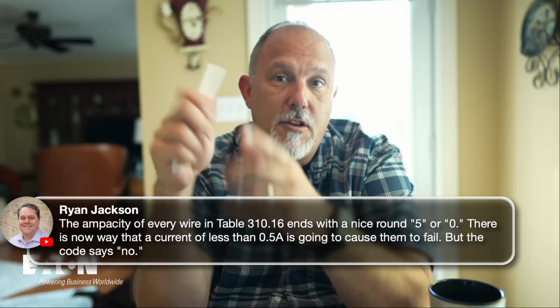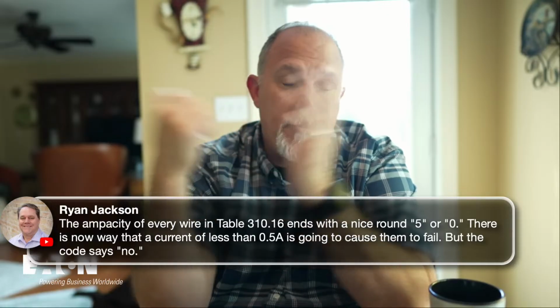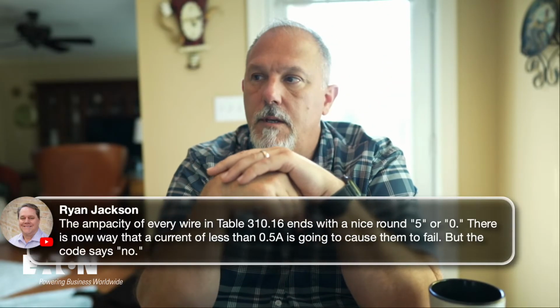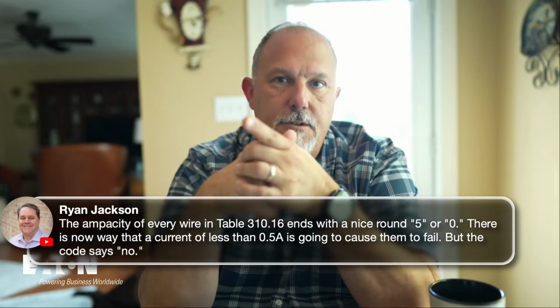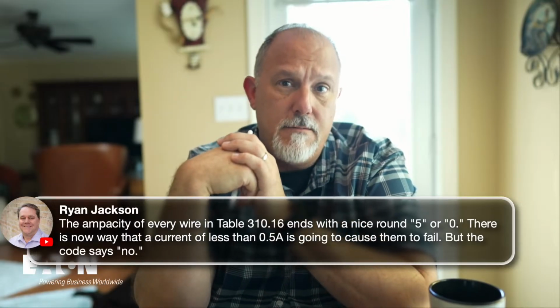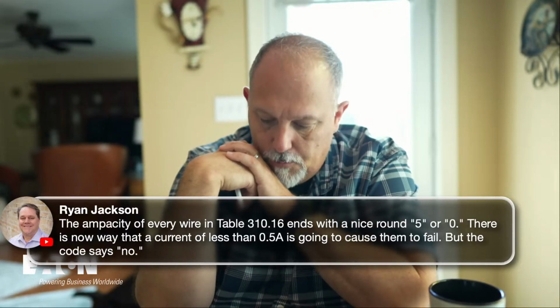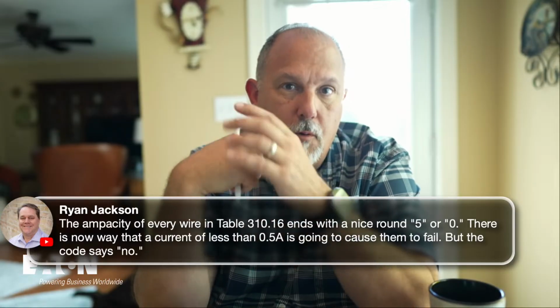To support your argument, Ryan, if you make a public input, I'm not suggesting that you do, but if you do, I would argue that on these conductors, you can go to the next larger overcurrent protective device, not 0.05 amps, or 0.5 or 0.4 or 0.1.